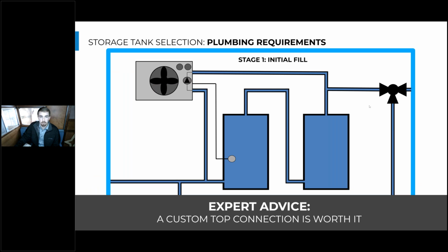So to see this in practice, we've simplified the system a little bit, and I just told you that in practice there should be this separation between the heat pump and the mixing valve. But this is an old animation, and it really illustrates how the stratified storage works when you're bringing really cold water in from either the city or from the bottom of the tank and heating it up to 140 degrees.